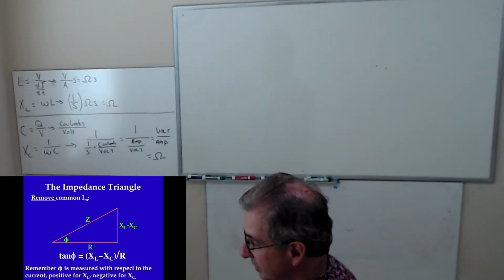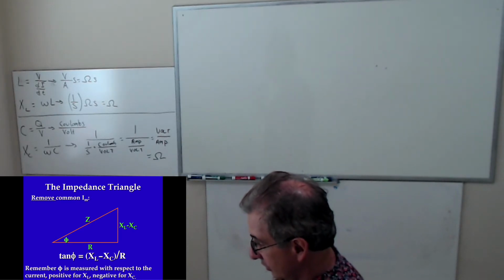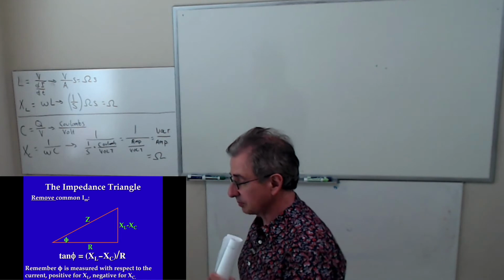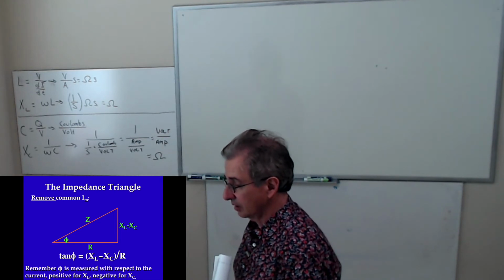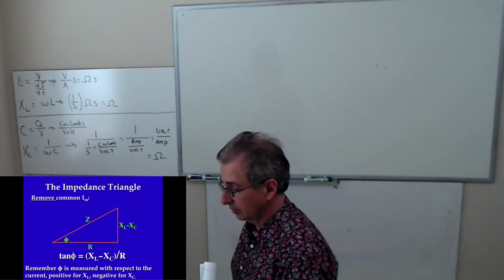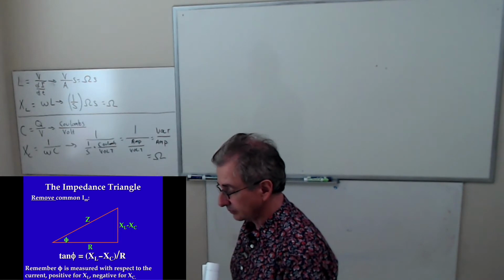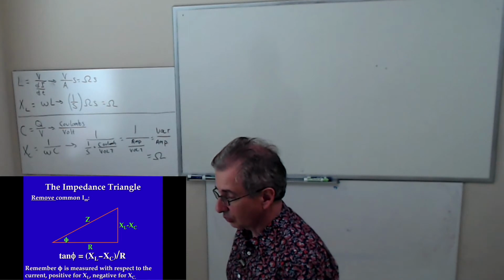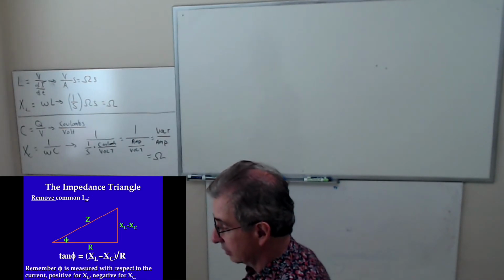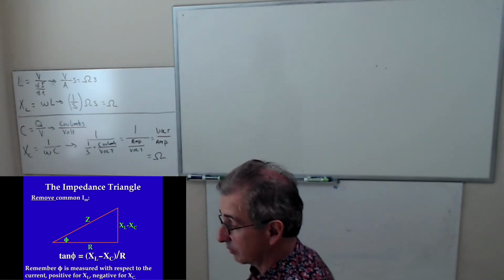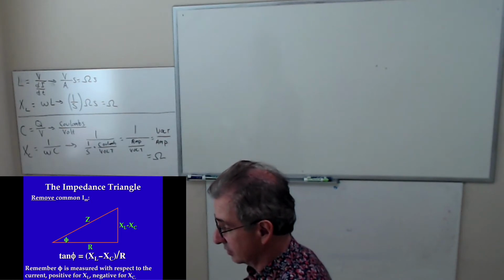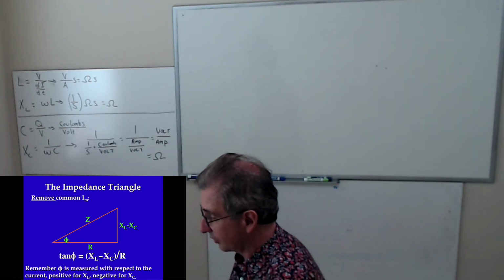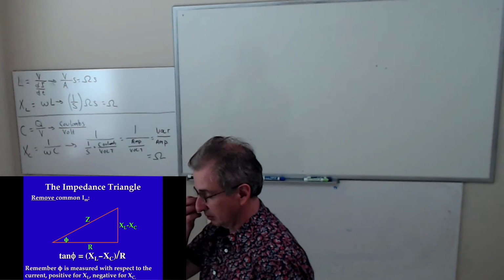All right, so regarding the question in the chat, you're supposed to set the power supply voltage to 1 volt, peak to peak. If you measure it with the multimeter, then you're going to be measuring the RMS voltage. That's all it is. And you should record that.